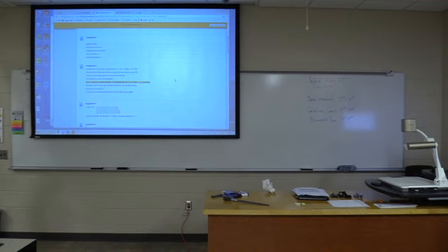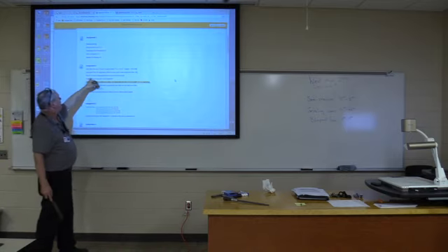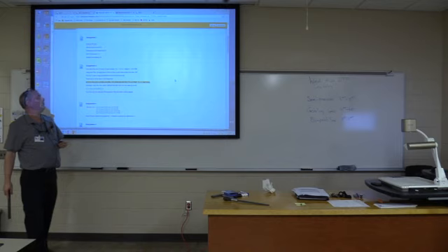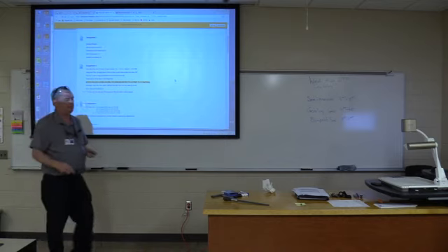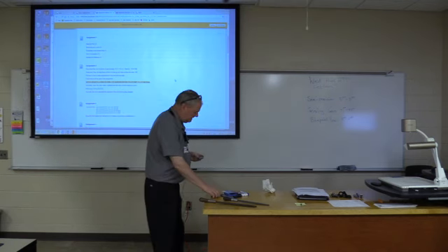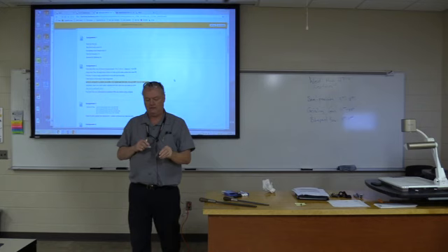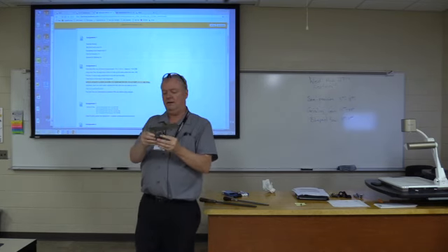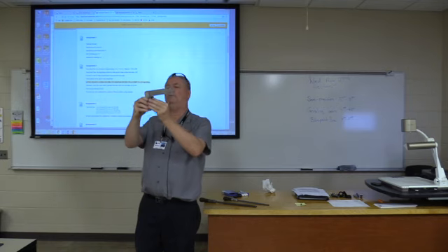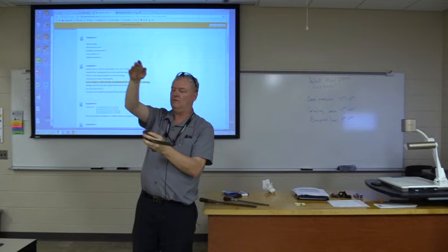You can take a look at this block later and you'll see that there's just a few scratches all through it. But now it says, using hand files, file one saw cut edge perpendicular to the top and one long edge. So what does that mean? That means that you look at the edge that you saw cut. You use your machinist square, and if you put it against the square like that and put it up to the light, you're going to see the face is either going to be like so or like so.